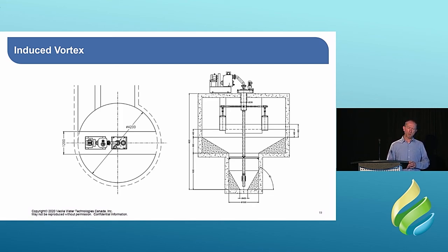What we're looking at here is a pretty common design. Some people would call this a 270-degree grit chamber, and that's because of where the influent comes in. Looking at the plan view, the smaller channel on the far left there is the influent channel. It comes in right on the tangent, right on the edge of the round chamber. Then the flow goes around about 270 degrees before exiting out of the other channel, the effluent or outlet channel, right at the top of the screen there. So that's about 270 degrees of rotation. That's why they're called 270-degree grit chambers.